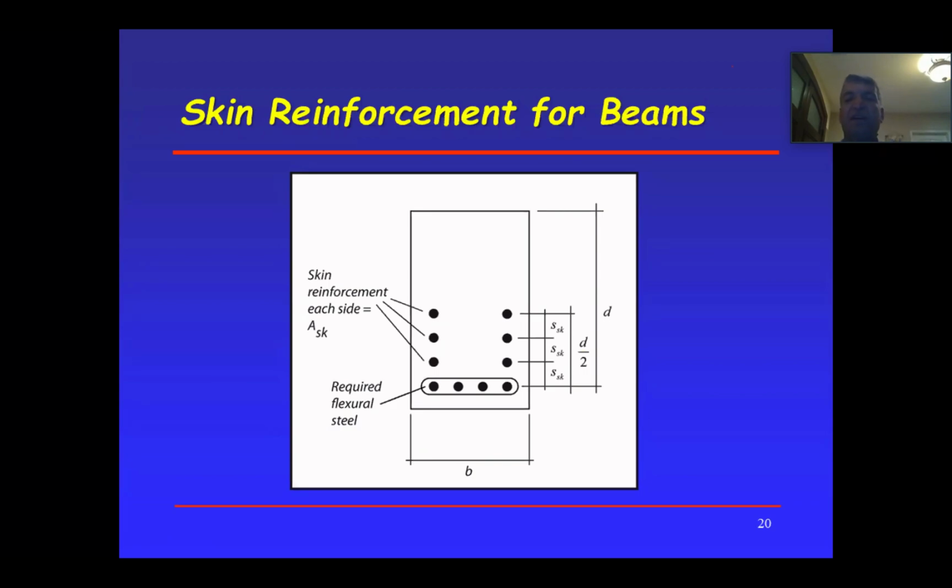We cut it down to 63. We make the 20s, we make them 19, sometimes 18, depending on the city standards. But if you're comfortable, make them 20. It's the best. 19, yes, we use 19 sometimes. So if that's your span length, the moment is wL²/8. L squared, see that? You're squaring the length. So the longer the beam, the higher the moment is going to be. So what can you do to manage that? You can reduce the w, the load. How do you reduce the load? By reducing the tributary area.